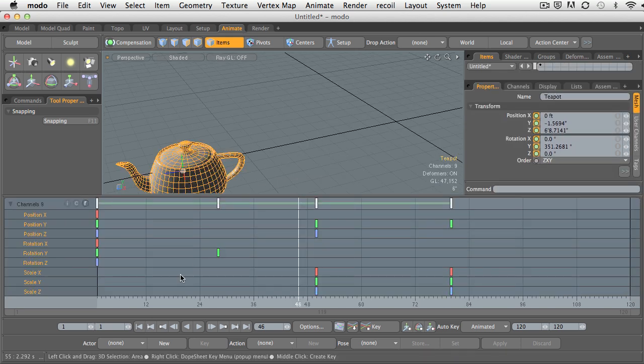Now, the dope sheet has a lot of the same features that we just saw over in the graph editor, but what we can't change is the value of the keyframe very easily. But we can, however, change its position, its location inside the timeline. Again, just by left-clicking and dragging on any of these vertical little rectangles will allow us to very quickly go in and change where these keyframes show up inside of our timeline. So this is kind of a handy-dandy feature.